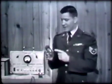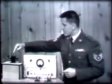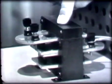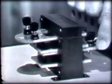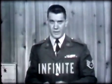Now, of course, the greater the number of turns shorted, the greater the decrease in the resistance of the winding. Now, it's also possible for one of the transformer windings to be shorted to the core of the transformer, or even for the different windings to be shorted together. However, these troubles can easily be located since the resistance between any two windings or between any winding and the core should always be infinite.